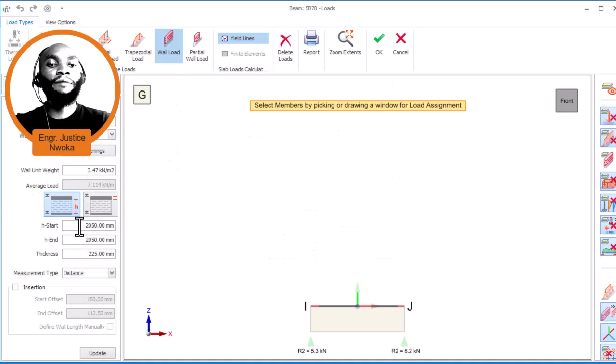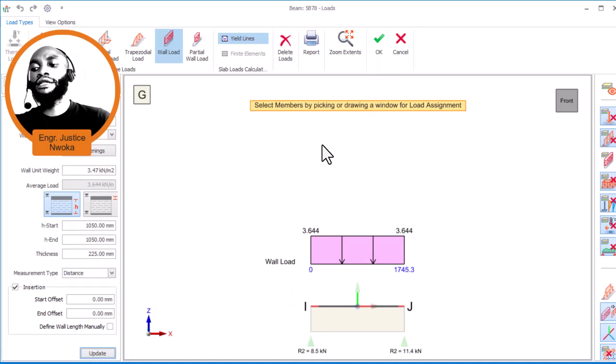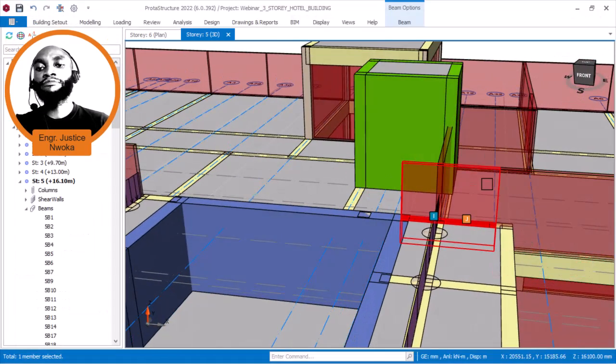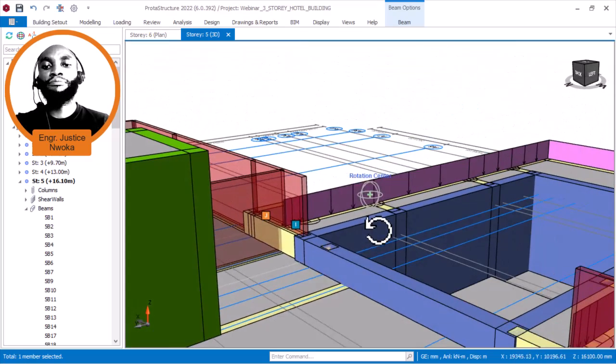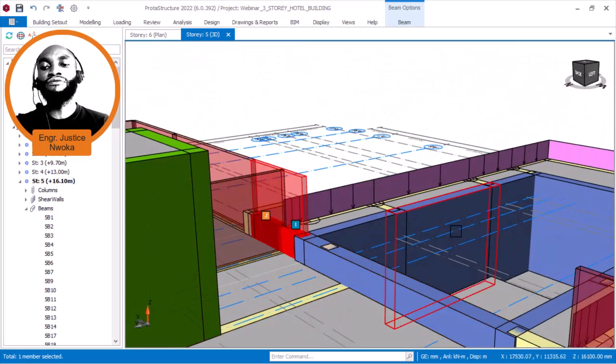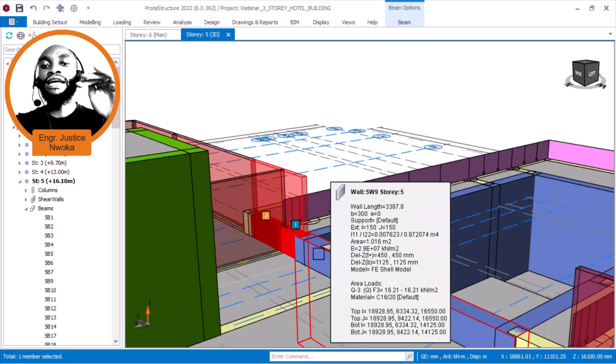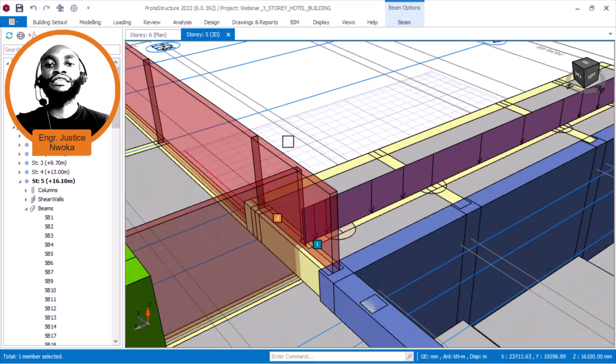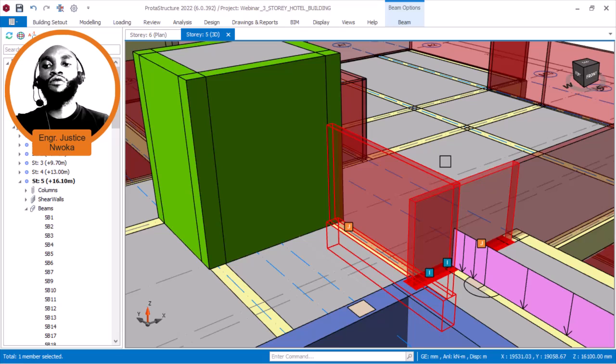That's because we have that place elevated before, 1050. Okay, and then come here, insert point 0 and 0, insert it, update, and then come here. Now the reason why I did that is so that it can have the same level. Can you see that? It can have the same level. That's because don't forget that this place here has a step that caused this pool area to elevate by 450. So with that now we need to subtract it, because now here is higher than here. So we can have the same level. You can see the same level of the parapet load.